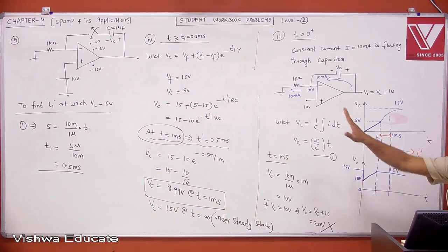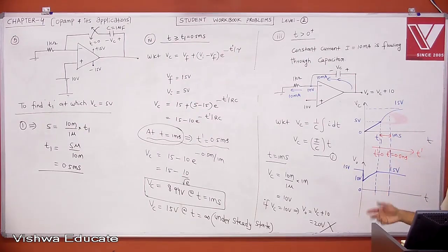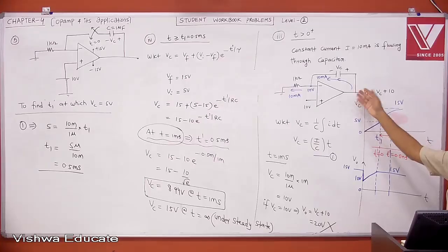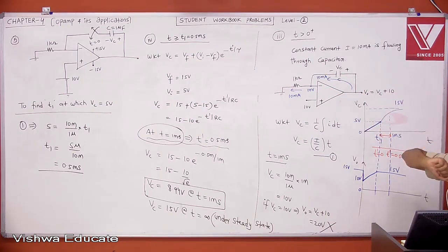If you assume that the op amp is ideal, you will get 8.94 volt. But people solved it instead of taking all these things, which is complex. You just take that your capacitor will be charging exponentially. Don't take any virtual current concept, just take it the transient way, which is not correct. Then if you solve in that way, you'll get the answer which is 9.45 volt.